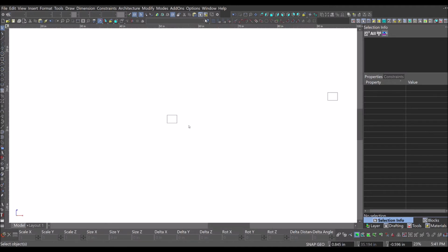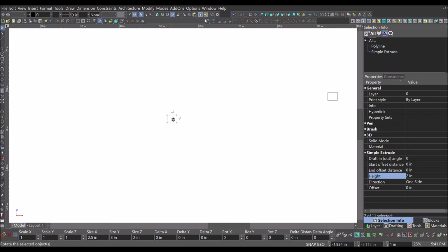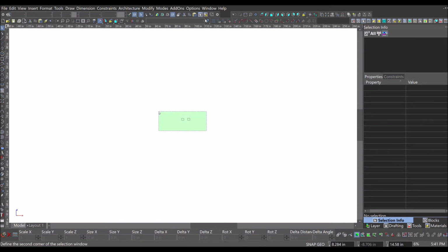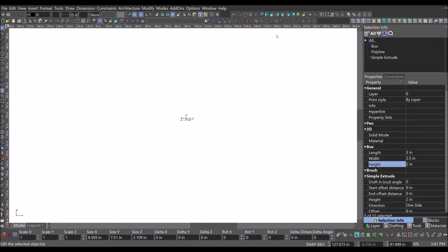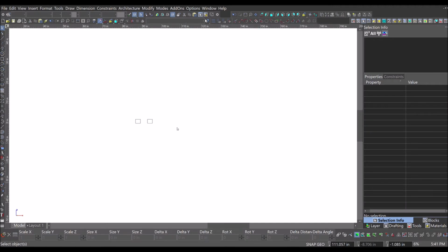And just for your information, I've got the accuracy set up on this particular drawing for an accuracy of 3 decimal places, rounding off at 5,000. So that's how I got it set up. I can give you any accuracy you want out to 6 decimal places if so desired.